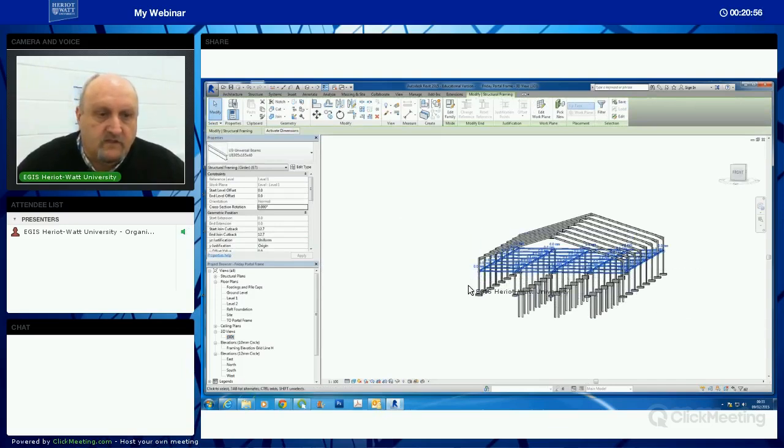Now the default concrete slab floor has a rather odd dimension. It's 211mm thick in this template. I'm going to change that to 250, and therefore I want these beams to be offset down the way, both in the start level offset and in the finish level offset of -250, so that the beams don't occupy the same 3D space as the concrete floor which they're supporting.